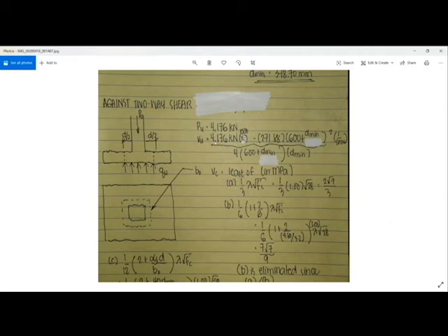Vu is equal to 4,176, this is our factored load, the 1.2 dead load plus 1.6 live load, multiplied by 1,000 kilonewton, converted into newton, minus 271.88, that is your qu, multiplied by (600 plus d minimum) squared, times 1 over 1,000, because I converted your 271.88 into megapascal, over 4 times (600 plus d minimum), that is your b_o, times d minimum.